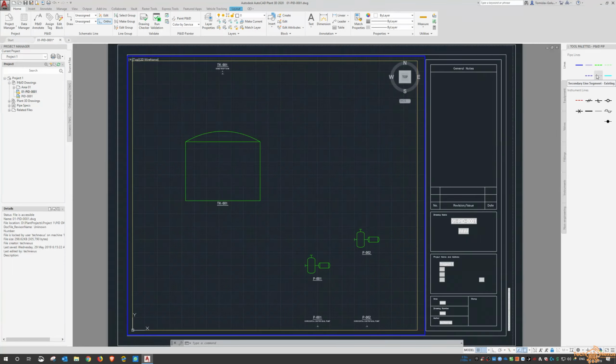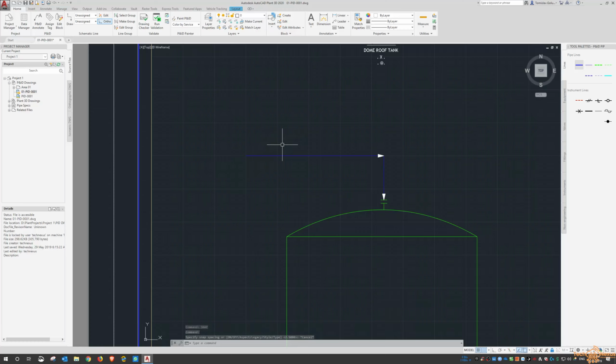So when we start, I've got my idea here for that line, and I've started it at this grid here, and you'll see my grid values. I'm set to 5 for the grid and a snap of 2.5. You have to take into account, if I'm going to do a second line, for whatever reason, that we need to do another line close to it. So that's the kind of grid spacing that you might want to look at as well.